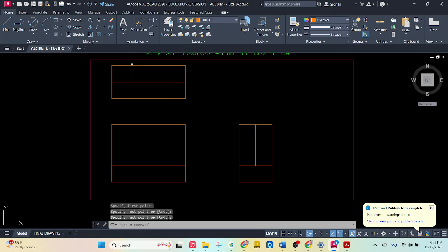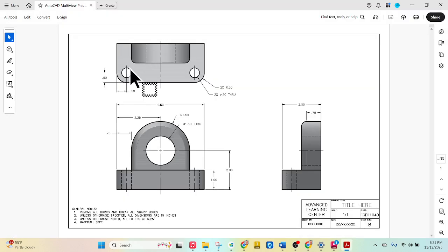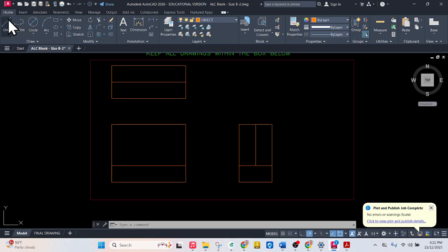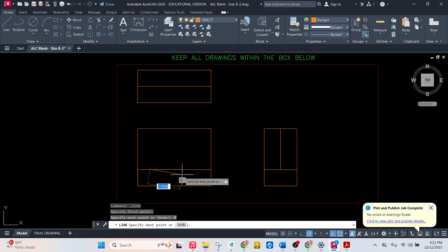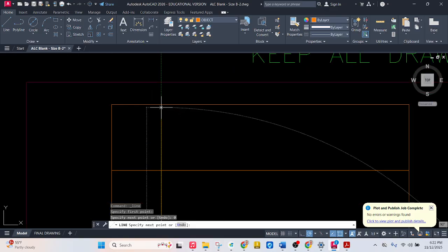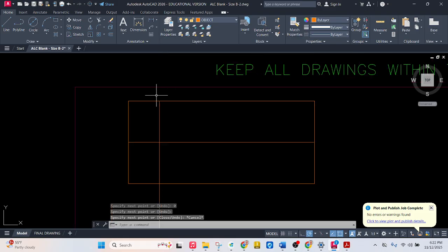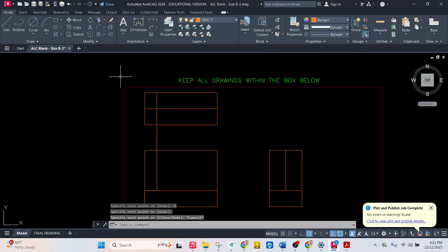It is. And then there's going to be a line that goes down to define this, like right here and this right here. So this goes in 0.75 and then all the way up. So let's try that. I'm going to go down here, 0.75 tab 0, enter, and then it goes straight up to the top. And then I can use the mirror tool to get that same one on the other side.